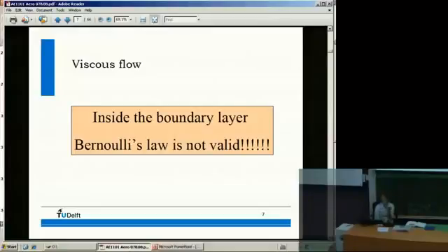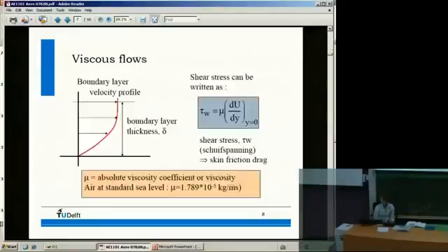And you cannot apply isentropic flow relations either, because it's really irreversible. Friction is a process where kinetic energy, speed, is transmitted into temperature. So you have a temperature increase. For aircraft, it's not so important, but for, for example, re-entry vehicles, it's quite crucial.